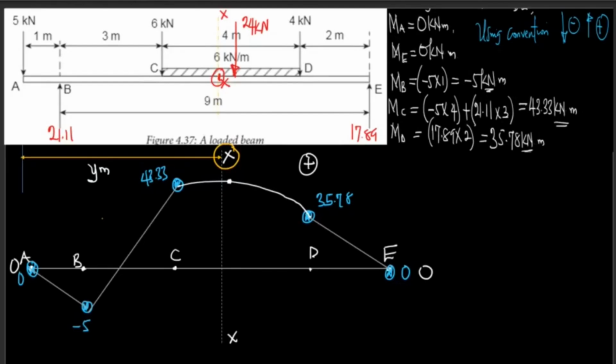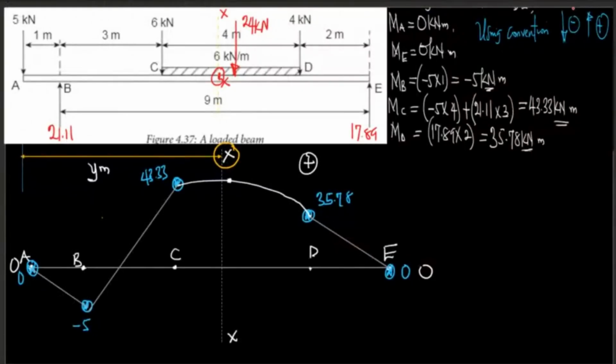The only way you can differentiate them is, like the axis, you can draw it faint, maybe 0.3, and then draw your actual graph with maybe 0.7 or 0.5. No, don't do it on the same axis. Like I said, you have to draw your bending moment diagram just beneath the shear force diagram, and don't use different colors. It is not allowed.